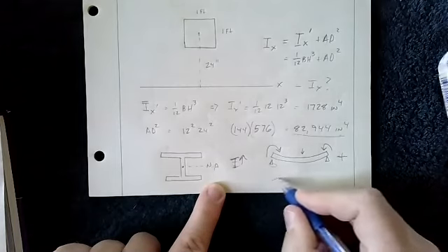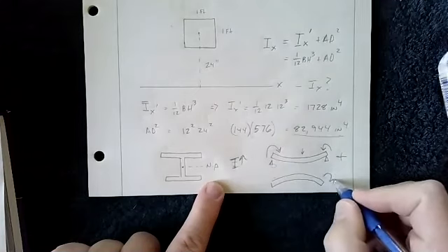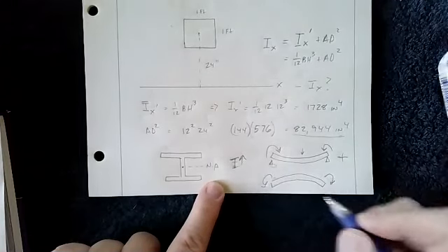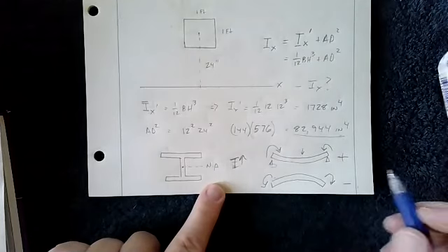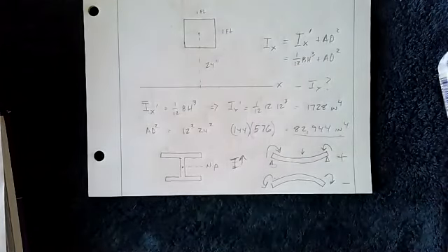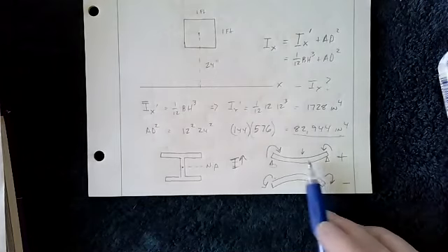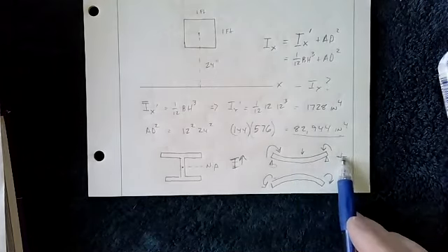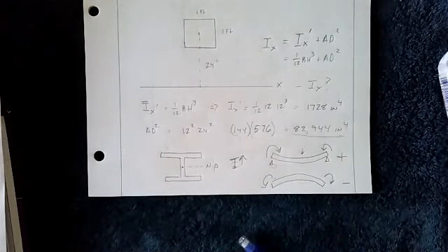And if you have a bending moment that looks like this, where it's bent out like that, that's considered a negative bending moment. Now, in other countries, I think in Australia, it's the opposite, but in America, we use this convention. You can always remember because this bending moment's smiling, so it's positive. This bending moment's frowning, so it's negative, okay?